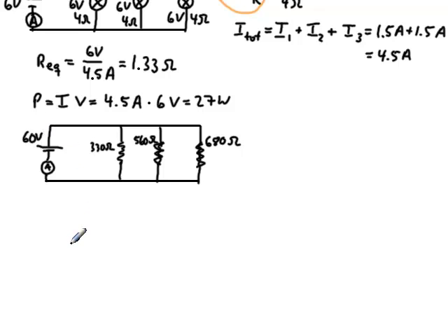Okay, the same rules would apply. Each device connects to the same 2 points of the circuit, the voltage is therefore the same across each device. So actually that one we do know, 60 volts across each one of these. Okay, then the current divides among the parallel branches.